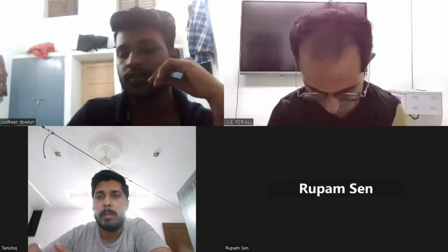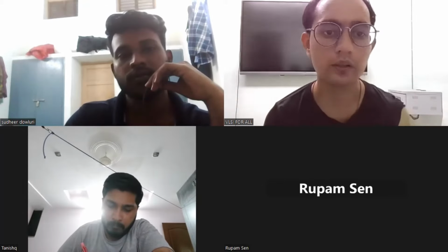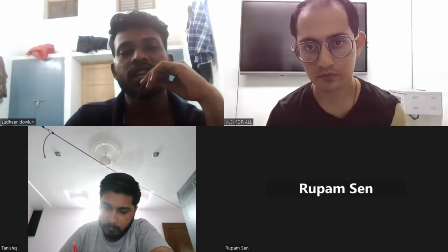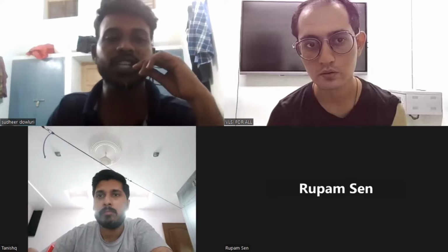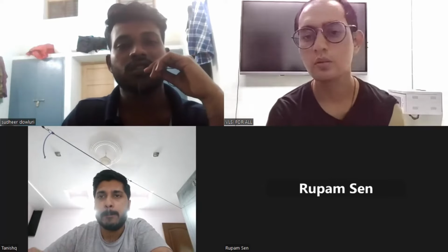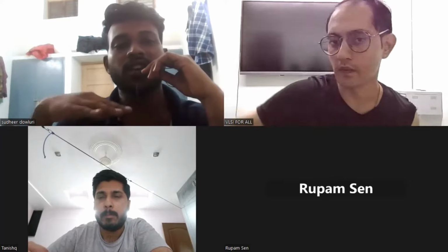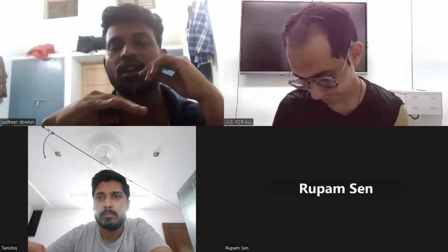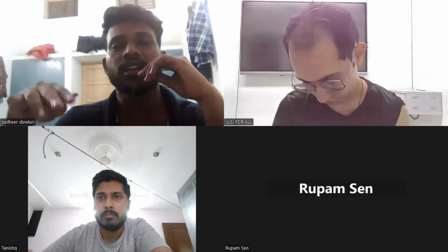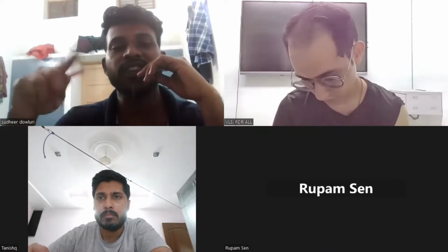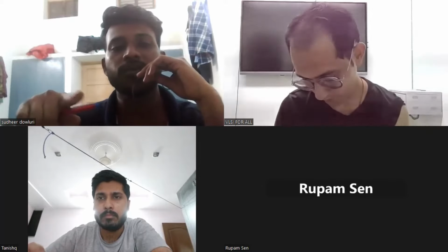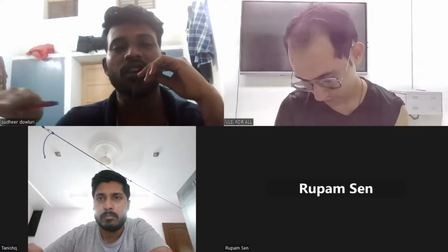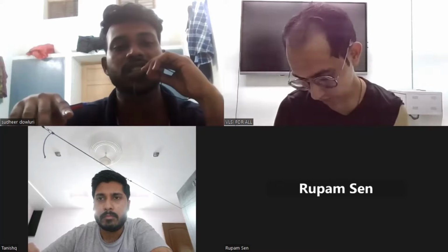Right? Check it after. So, what is the disadvantage of JK flip-flop? When the input is 1-1, it will toggle itself. It causes the race around condition. So what is the race around condition? When the clock input is high and we give input as 1-1, the output will not be stable. It will go 0-1, 0-1, 0-1, 0-1. It oscillates like that. That is the race around condition.